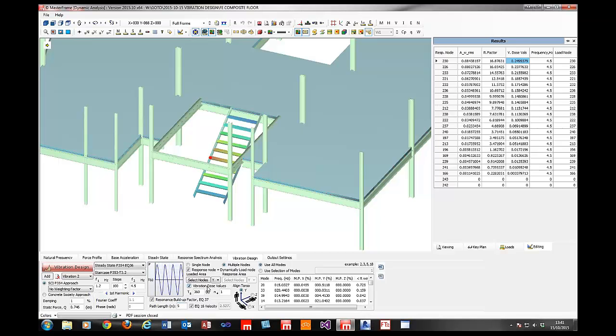In other instances, it might not have any effect. So it's worthwhile taking that into consideration. So really both of these options here show us that the steady state response really is your worst case scenario of somebody continuously interacting with the structure, and you can mitigate against that or do something more realistic with the combination of these two options.